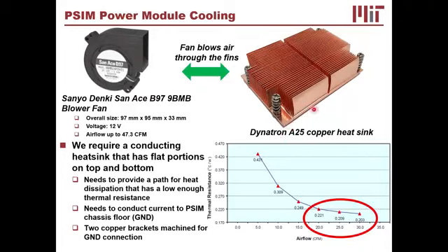So I'm going to connect the heat spreader onto this Dynatron copper heatsink. And here's what you can see about this heatsink: the thermal resistance to ambient of the heatsink versus airflow. This is where I said, to really know this heat transfer coefficient is a lot of work, and to design the heat sink to get a high heat transfer coefficient is hard, but somebody else did that for me. All I've got to know is how much air I'm going to blow across this, and I can get down to crazy low thermal resistances. If this wasn't low enough, then I'd have to go to liquid cooling and get even lower ones. But we were able to do it there.